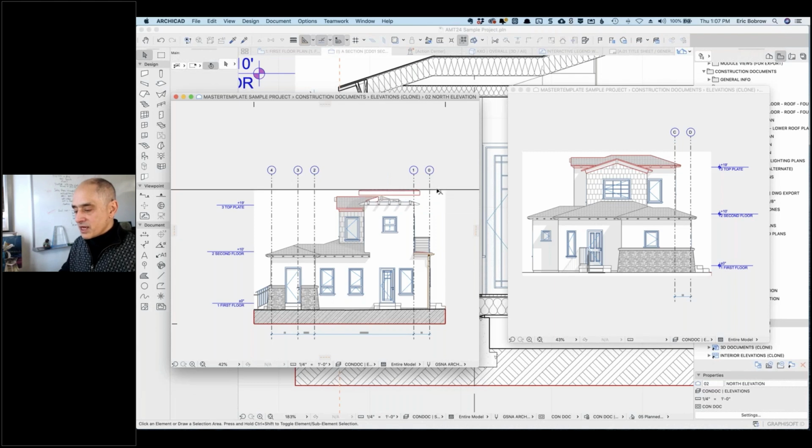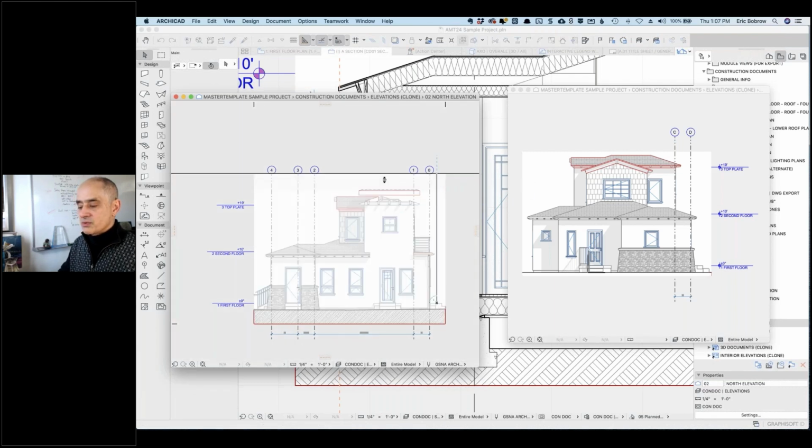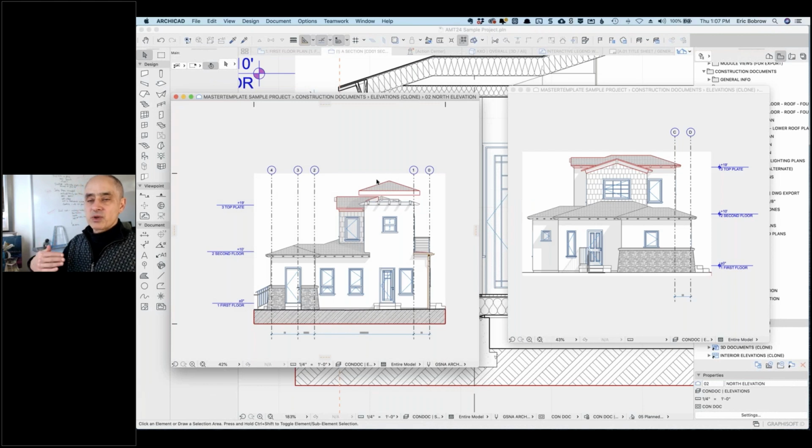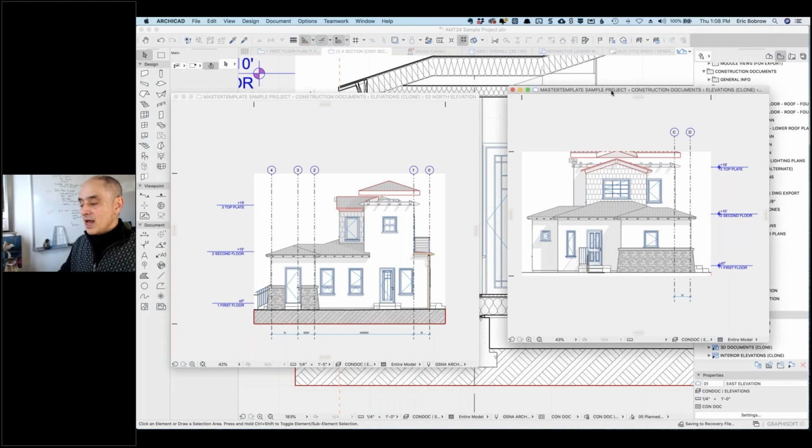Okay, and then change the boundary here. The elevation in this case has a boundary set saying it's only going to go up to a certain height. Probably not too important going up, but going down, you may want to restrict it so that it's not going super far down or necessarily as thick as your terrain mesh. But you notice I changed it here. We aren't seeing any change there. So in order for it to change, I need to click on it. And then you can see all of a sudden it's flipped up to this orientation.